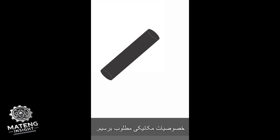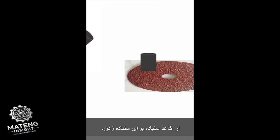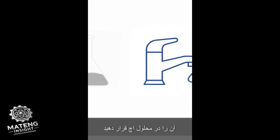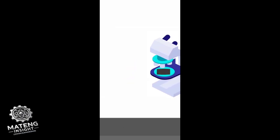To observe microstructure, you just need to cut a small specimen from a part, utilize sandpaper for sanding, polish it, put it into the etchant solution, and then put it under the microscope.